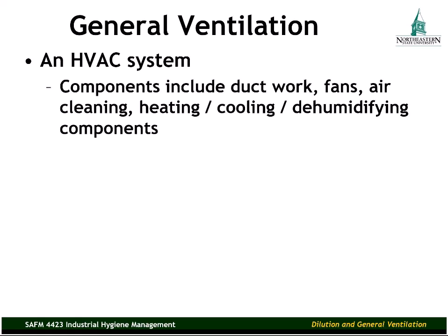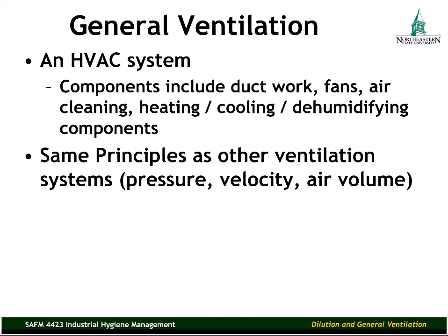The components are there, the ductwork, the fans, the air cleaning elements, maybe heating, cooling, or dehumidifying components are included in a general ventilation system. Also, the same principles are at work as are in other ventilation systems. Pressure, velocity, air volume, fan laws are applicable to general ventilation systems. There's a lot of overlap between all of these different ventilation systems.